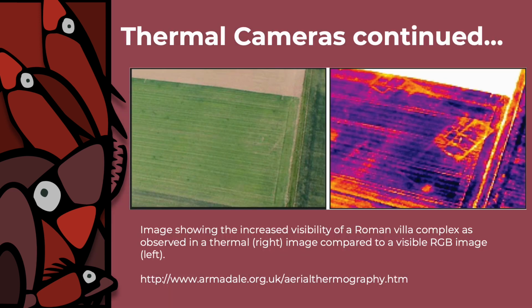There are, however, some limitations. Firstly, buried features such as a wall or a pit are only potentially visible if there is sufficient contrast in the thermal properties between the feature and the surrounding soil. Secondly, this technique only works for features that are relatively close to the surface. It is important to understand, therefore, that we are not trying to identify the burials or coffins themselves, but rather the pits or grave shafts within which they are buried.